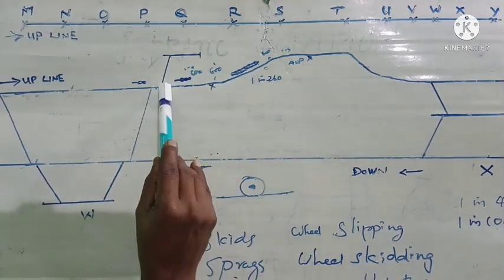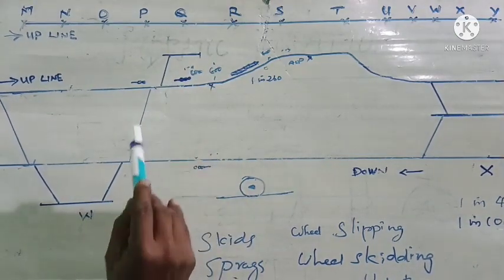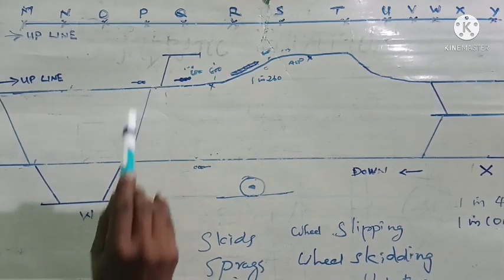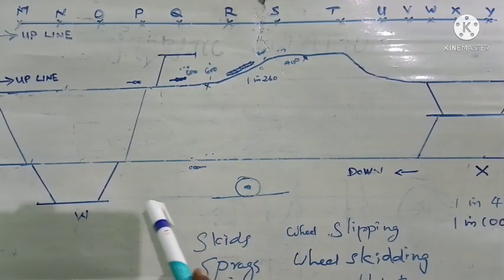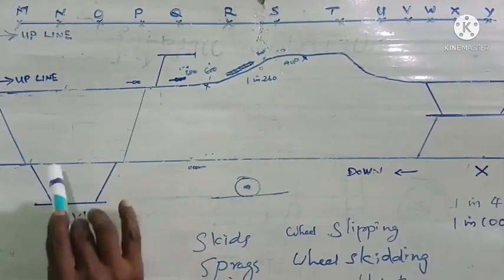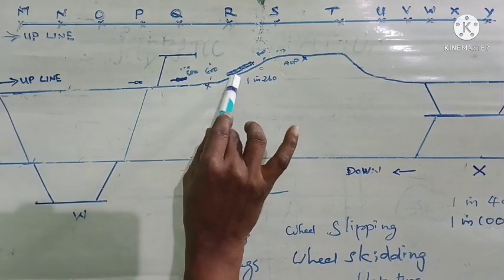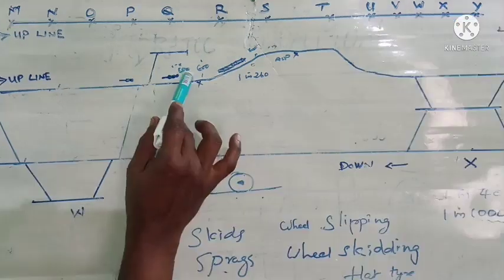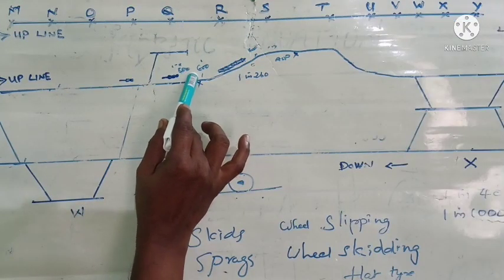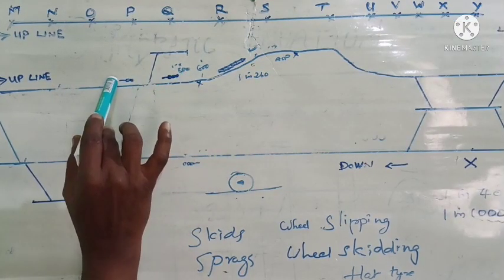So all these points over which the train is to move, here this one, here, all these points should be set, clamped and padlocked in favor of this train. Station staff will be taking the memo to the loco pilot and getting his signature in the duplicate. The train will be piloted by the traffic staff to the station.